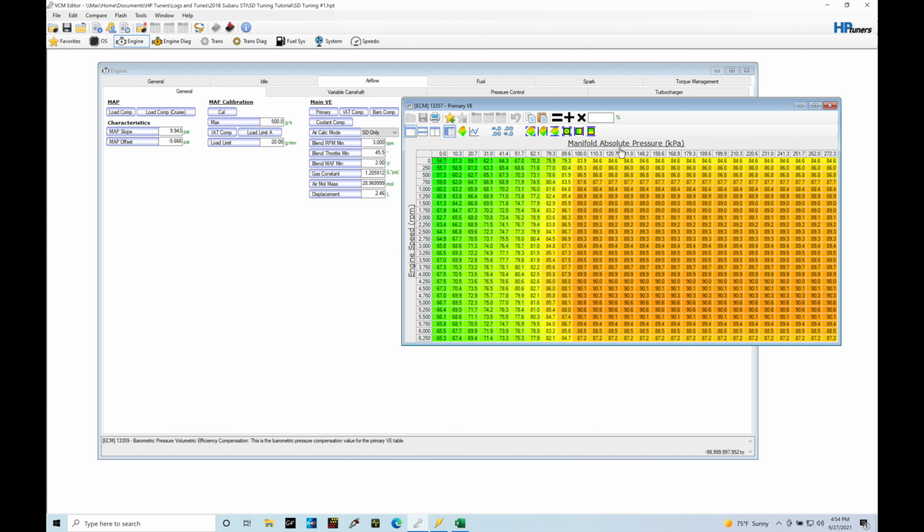We do not use the mass airflow sensor in the speed density calibration process. So if I'm calibrating and tuning this, I can eliminate the math. I can put whatever type of intake I want on my turbo inlet, and we have no issues. You can also vent your blow-off valve to atmosphere, so you don't have to worry about it blowing off and causing any kind of stumbling because we have a loss of airflow as we would with a mass airflow sensor. So speed density is really going to be nice for tuning high horsepower applications, or if you have a situation where you have a vent to atmosphere blow-off valve. It is not going to have any mass airflow built into the strategy. It's not going to be looking at that. You can completely eliminate it.